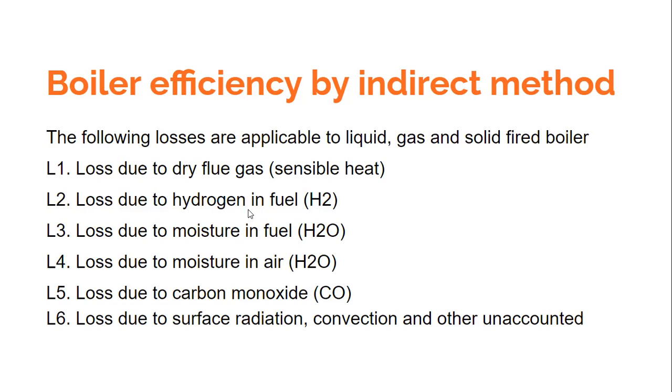Okay, then there is moisture in the fuel which would be evaporated. So there is again the heat loss because of moisture in the fuel. You can imagine that if you are using a dry coal and if you are using a wet coal, obviously the efficiency would be less with the wet coal, because there is certain loss in heating up that moisture and evaporating that moisture.